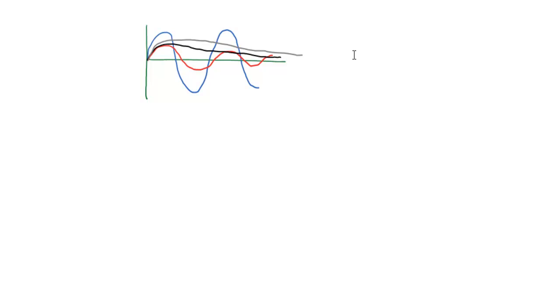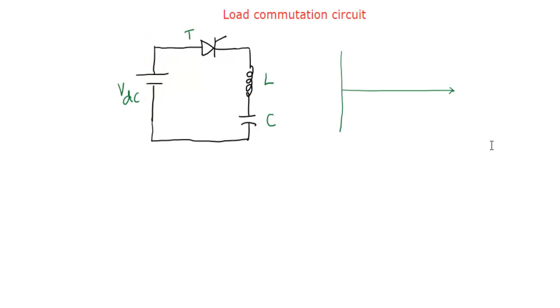However, we will discuss both cases, the undamped system and the underdamped system. The undamped system is theoretically usable, for solving GATE exam questions. For GATE exam purposes, we can also discuss the undamped load. An undamped load is nothing but only L and C. But remember, in class A commutation, the capacitor will not be charged initially. That's what you need to remember all the time.